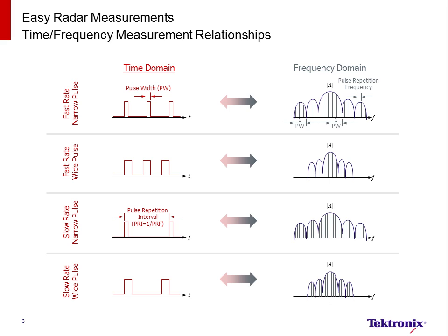Using a traditional spectrum analyzer for these measurements, you might already be familiar with this phenomenon. For the example shown here, the frequency domain information can be translated back into time domain for measurements of pulse width, which is 1 over side lobe span, and the line spectra from the pulse repetition interval, which is 1 over the pulse repetition interval line span. To have correlated measurements of time and frequency, a measurement system must also have sufficient sample rate, bandwidth, and memory depth to fully characterize the signal.